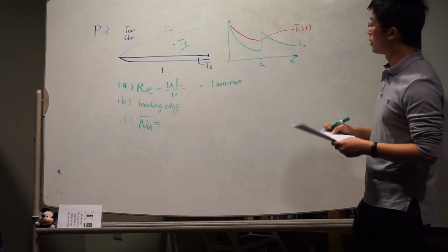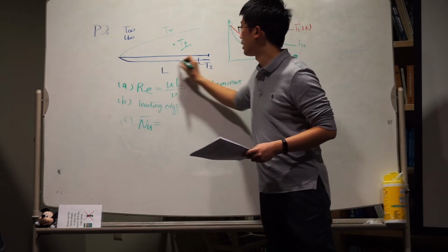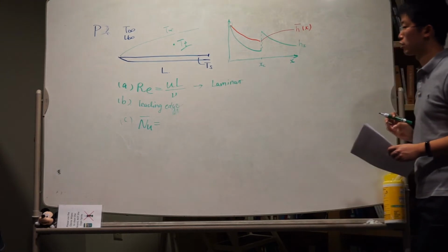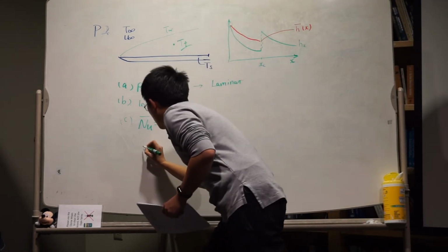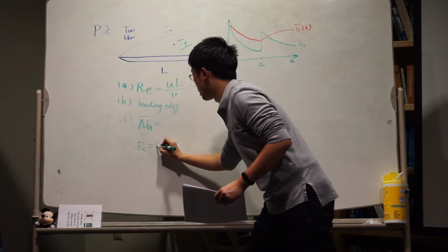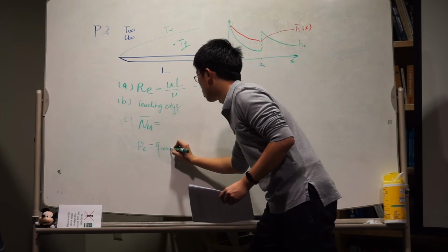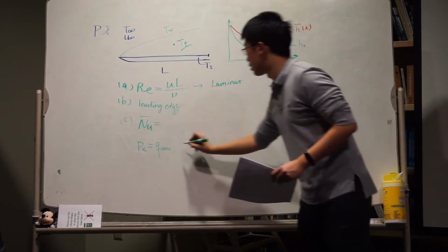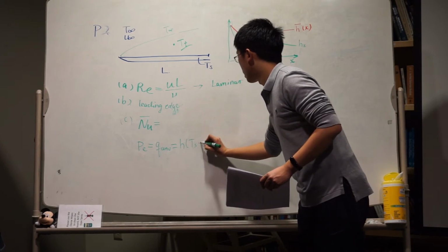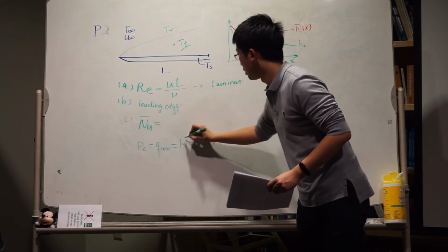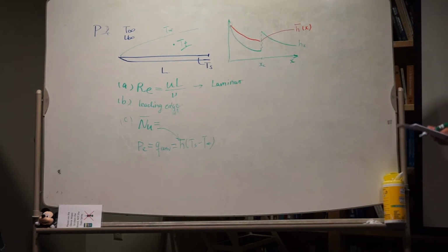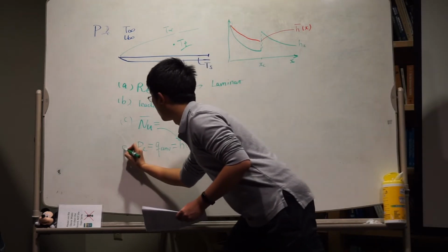And part D, there is some electrical heating within the plate, and this heat is taken away by the convection. So we will know the electrical heating power by energy balance: it should equal the heat of convection. And this one can be easily calculated by Newton's cooling law, and the coefficient is taken from the Nusselt number. Right, that's the procedure.